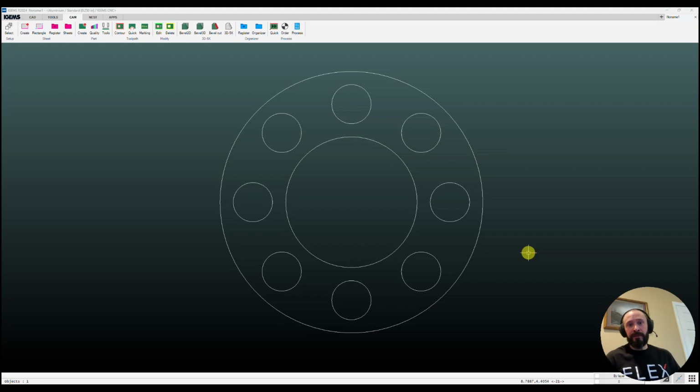We'll briefly go through initial setup, including defining your cutting head parameters, material type, and thickness, how to create a part out of a 2D geometry that you've drawn or imported, how to apply contours or toolpaths to that created geometry, a few edit tools if you want to make some tweaks, how to define your origin or start point and cut order within a program, and then ultimately how to post, process, and export your CNC file. We'll toss in a few tips and tricks along the way.